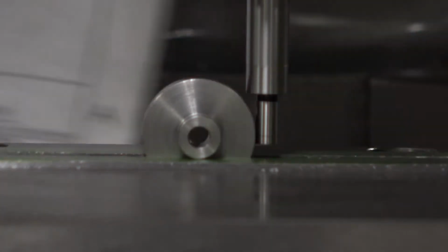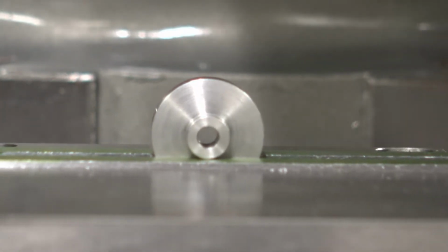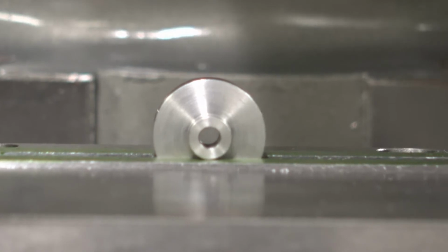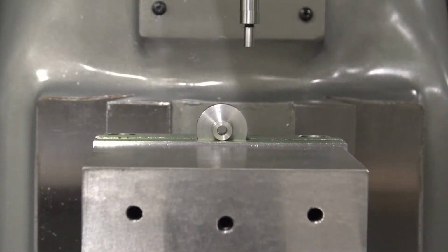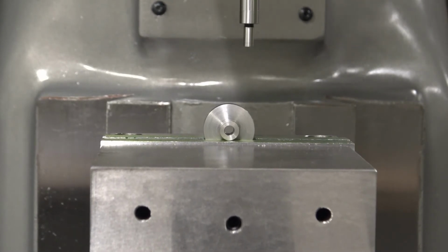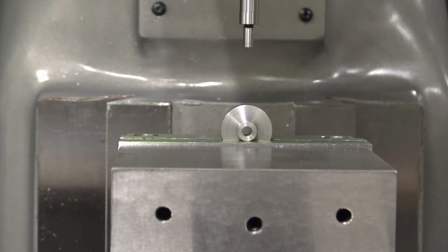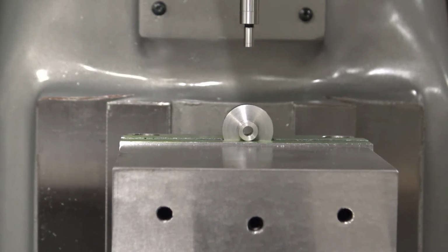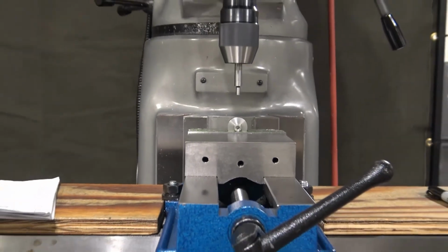Once we set our dial to 0, I'm going to go ahead and retract the quill back up. I'm going to move 100 thousandths. That's for half the diameter of the edge finder. And then we're going to move 500 thousandths more, which is 2.5 full turns. And we're going to finish up to be at 0 for you guys. And I lock the axis to the x-axis.